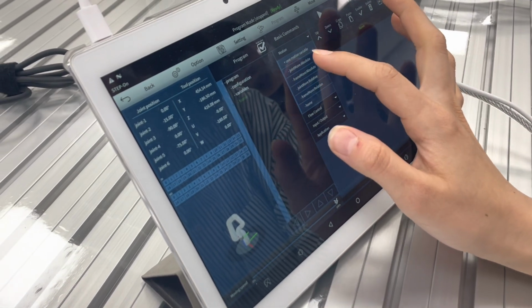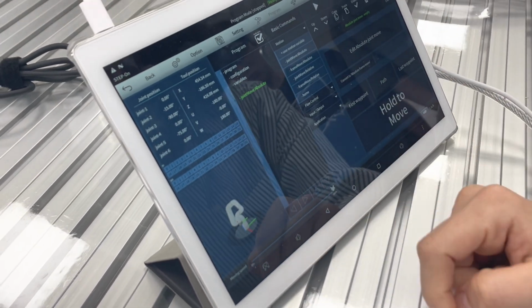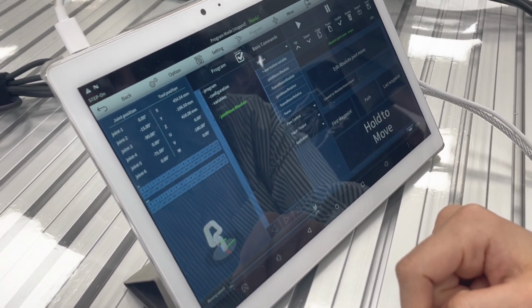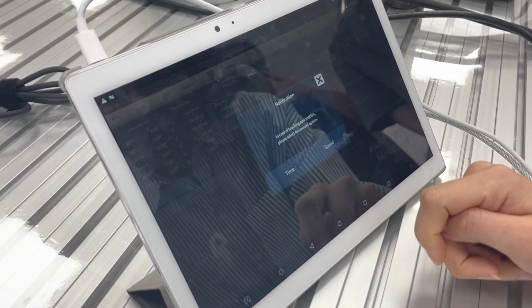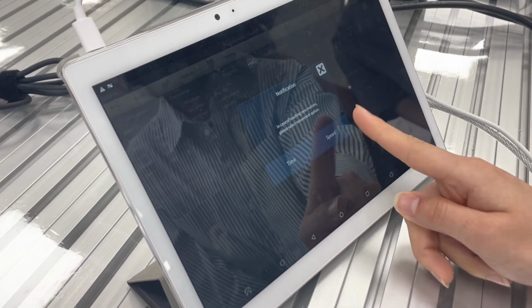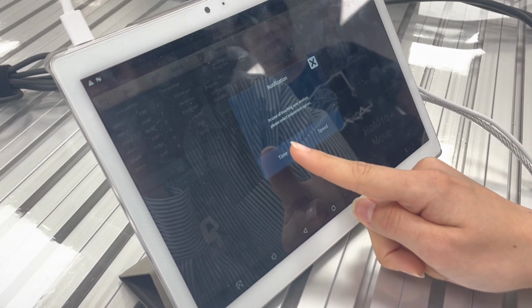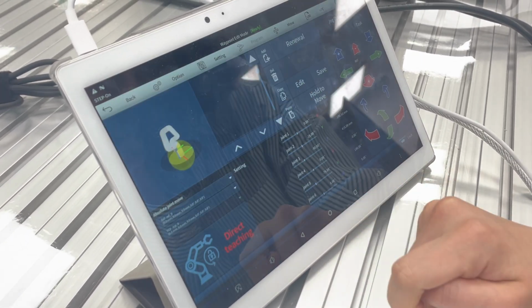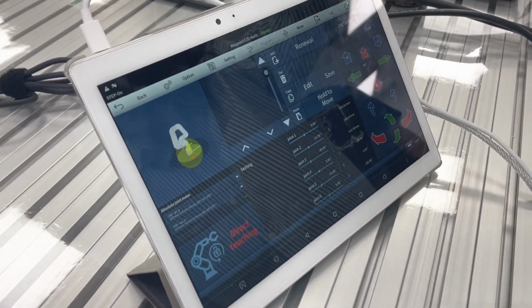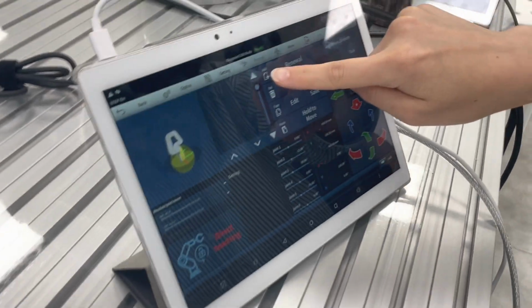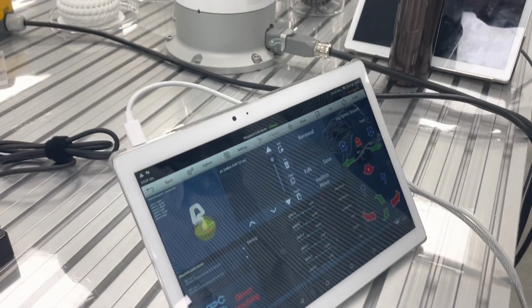First one will be this joint move absolute. We are going to add one movement, joint move absolute. And from here I can edit. I have to press this edit section. And we have 2 things here, time or speed. I will explain it later. Let's first select time. And from here, I would add the point that I am exactly in right now.